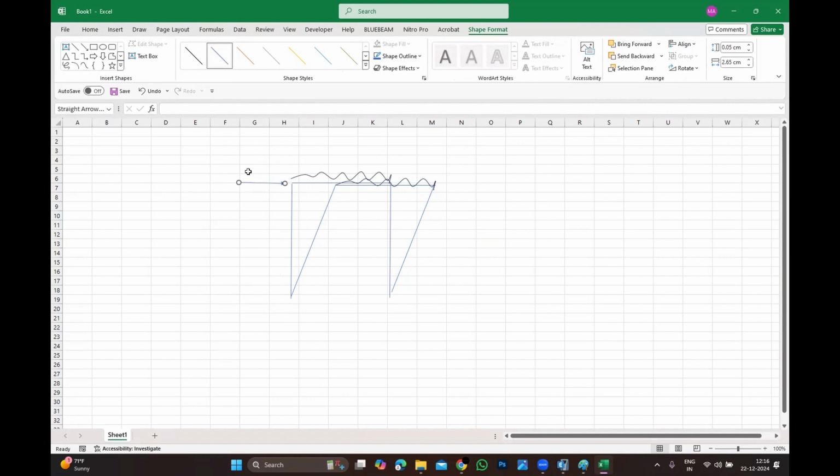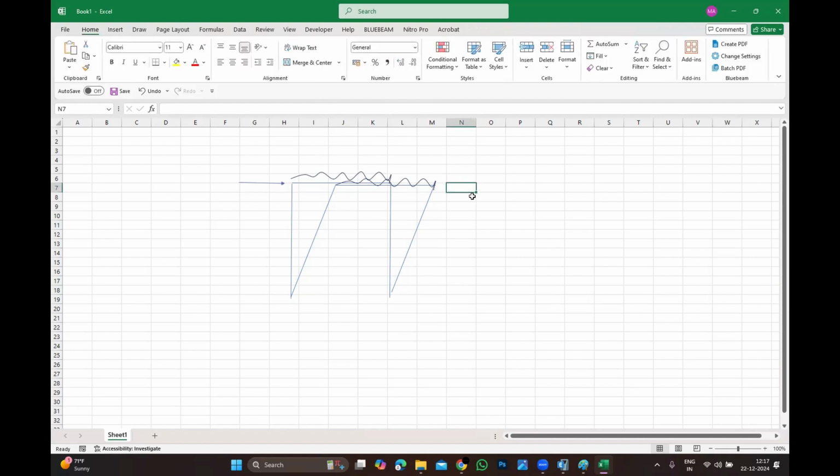Wind is going to come along the face of the structure. Any kind of lateral load comes, the structure is going to undergo sway. So in this case, what is going to happen? Your gravity load is also going to be displaced to a different location. So the CG of the original location to the CG of the displaced location is going to cause additional eccentricity. Then this P multiplied by eccentricity, you will get additional moment. You getting what I'm trying to say?